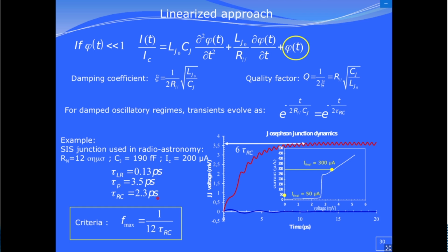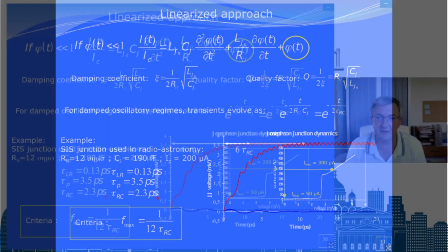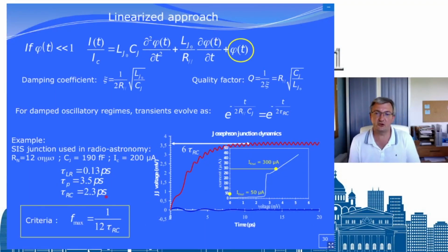But I can tell you, if you can find a material with a very low capacitance compatible with superconductors, we will make a big jump in improvement of technology. Material studies should be really essential now for new barriers, to do barrier engineering. But for the moment, we have what we have. This C you cannot change really. Usually it's aluminum oxide or MgO, but they are not very good. So the only way is to reduce the resistance, to reduce tau.